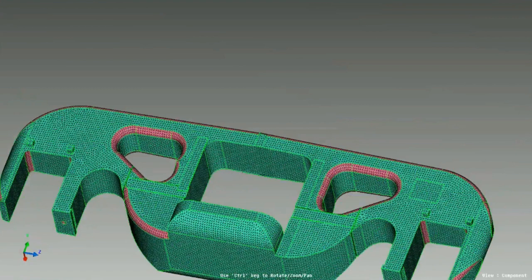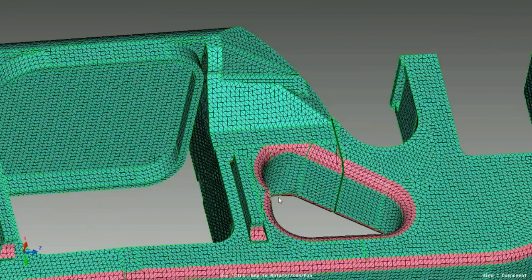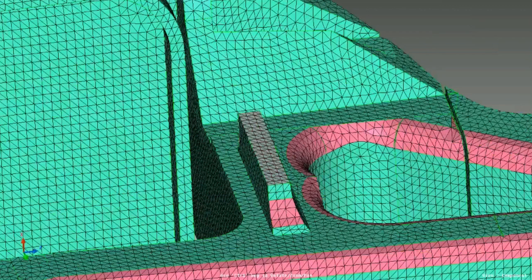And so we have some auto tools such as auto parameterization. Here we can directly change the values of the fillet radius and vary the wall height automatically with very few inputs. For example, if we have to change the height of this rib, the user can just select the face of this rib and specify the deformable layers and the range which he has to modify, and just click on execute.